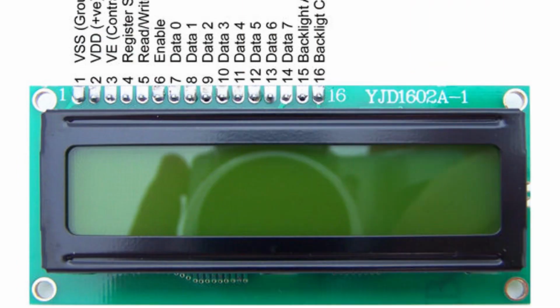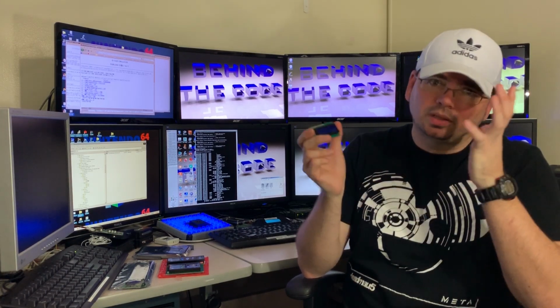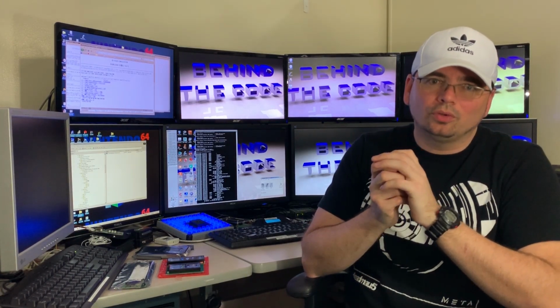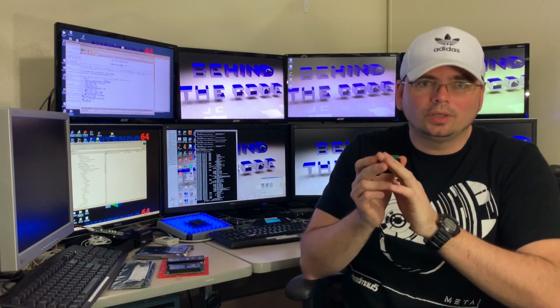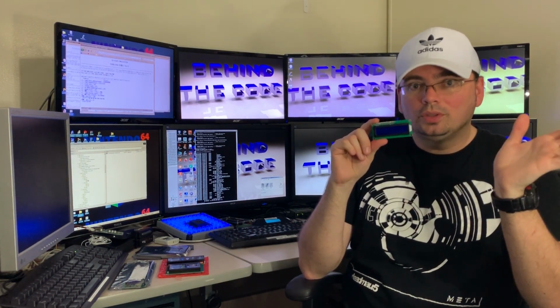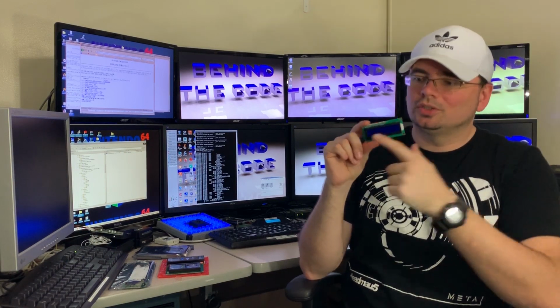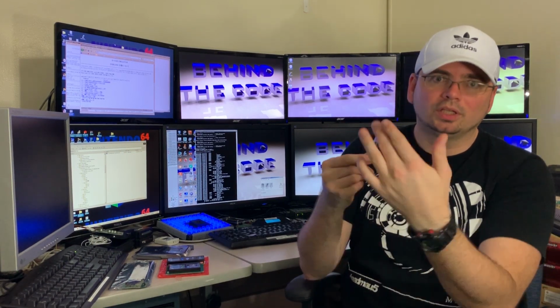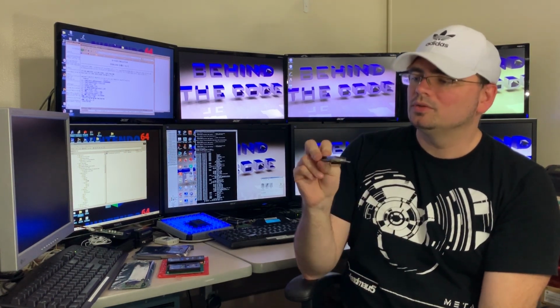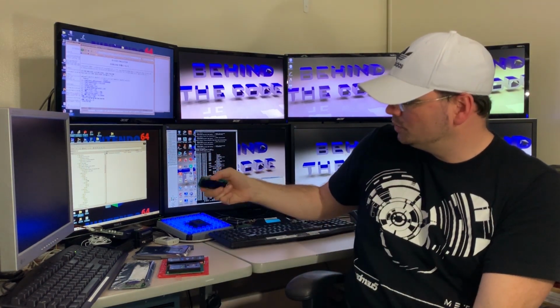Today's video, we're going to be looking at the HD44780 LCD displays and the standard protocol that goes with driving these. For those of you that have messed around with microcontrollers to drive these, like a PIC or an Atmel microcontroller, there would be a library you could use with the code to drive this. You could enter one command, say print such and such, and it would display it on the screen after you've connected and interfaced it using the basic standard interface to the Databus and the driver pins.